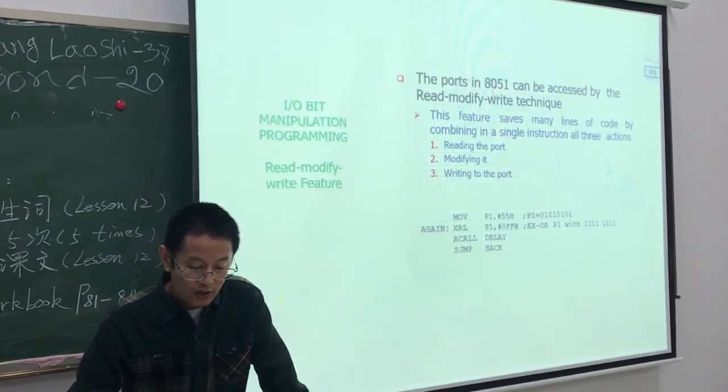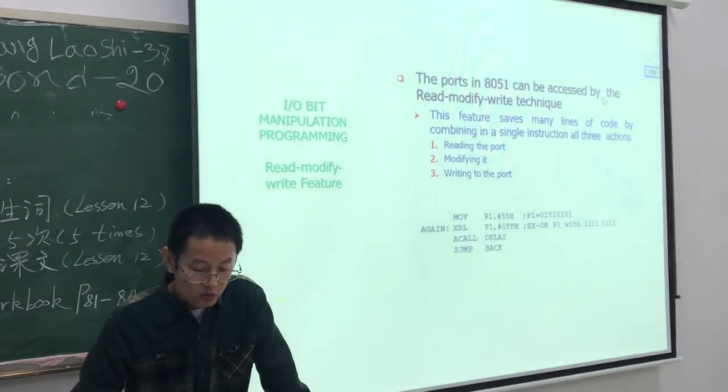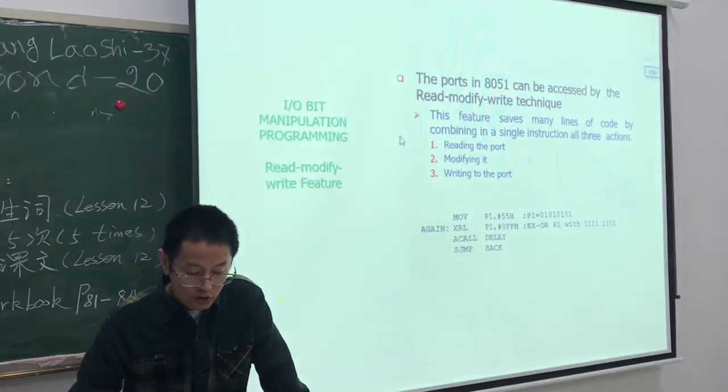The port in 8051 can be accessed by the read, modify, write technique. This feature saves many lines of code by combining, in a single instruction, all three actions.